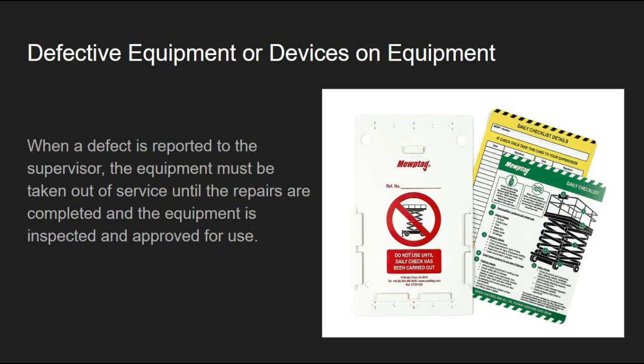If when you're doing your daily inspection on the equipment and you find something defective, remember, let your supervisor know and tag it out right away. Don't be using something that's defective, missing guards, or not working.